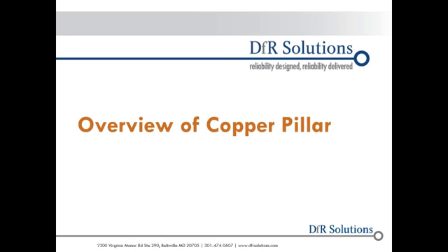It's a very exciting, newish first level interconnect between die and substrate. But as with most new technologies, there is a lot of hype and some degree of uncertainty about what the technology is, what it does well, what it doesn't do so well, and if it will make sense for you or your supply chain in terms of implementation. So hopefully today, I'm going to give you a nice overview of copper pillar, what the driving forces are, is it better than solder bump, and how it performs from a process and reliability perspective.